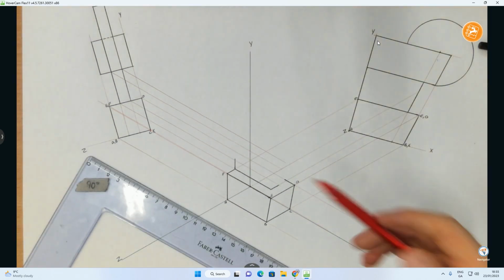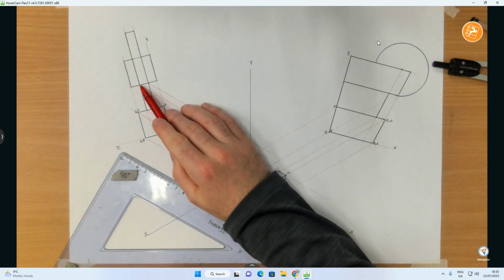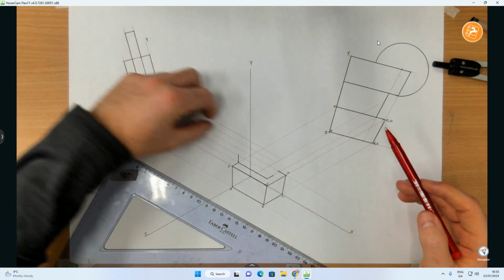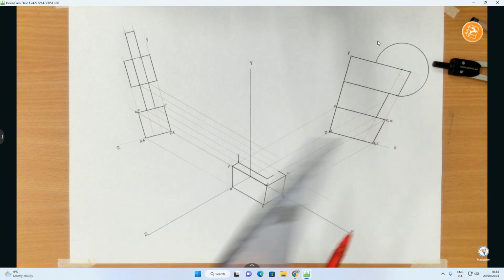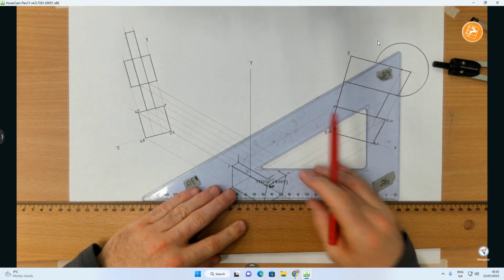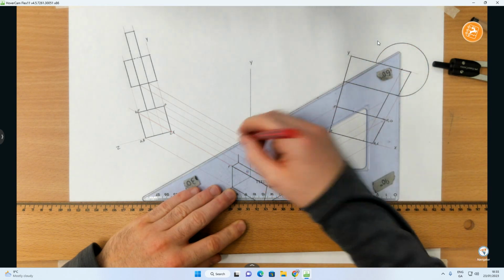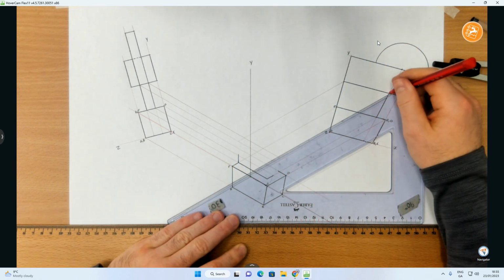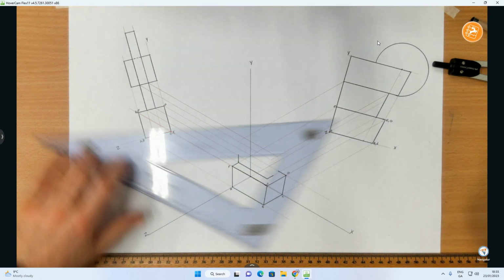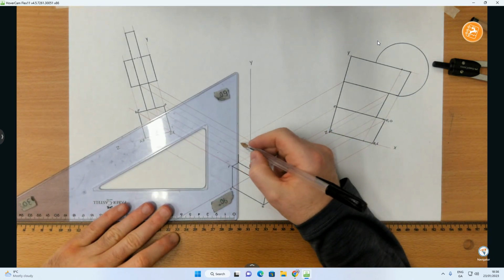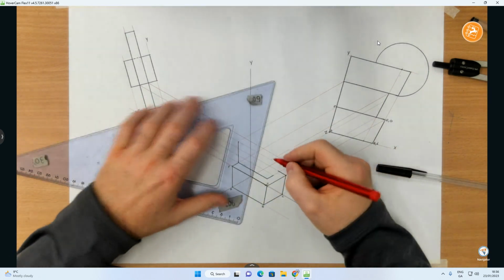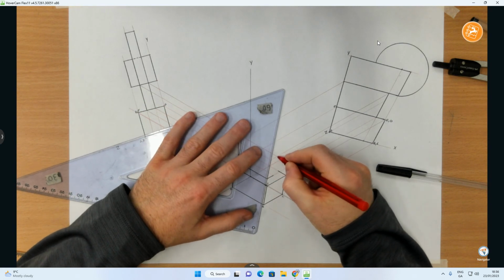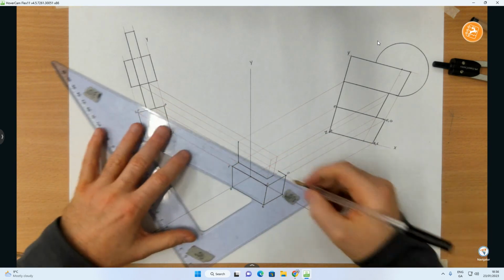Apologies. Should have zoomed out there, apologies. So what I was saying there was, this point and this point is that top portion in my end elevation. So I brought those two down. Now, where they are in this view, over here, is here and here. So at that point right there, bring that across, this point right here, this across. So there's that one. Probably shouldn't have heavied it in fully there. Apologies for that. Go back and I'll fix that in a minute. I'm slightly ahead of myself.